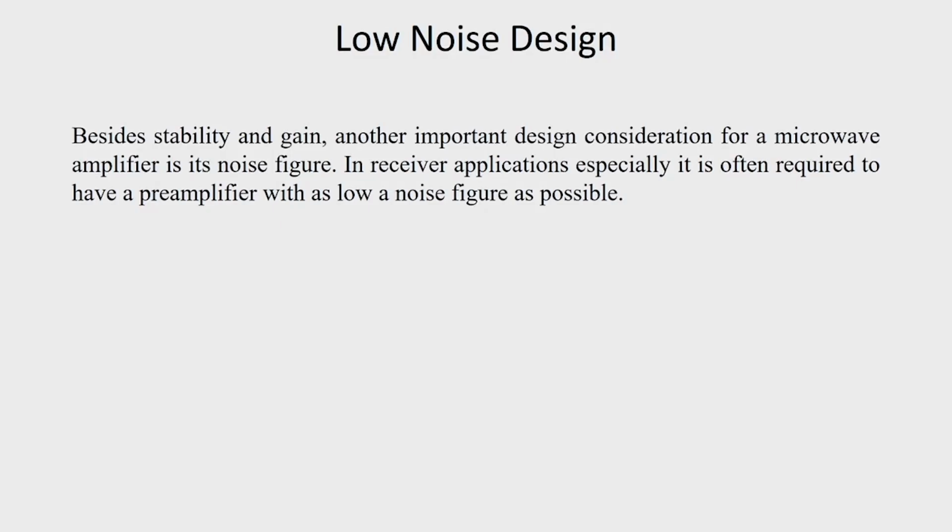Let us now consider another issue, the low noise design. Besides stability and gain, another important design consideration for a microwave amplifier is its noise figure. Particularly in receiver applications, it is often required to have a preamplifier with a noise figure as low as possible.